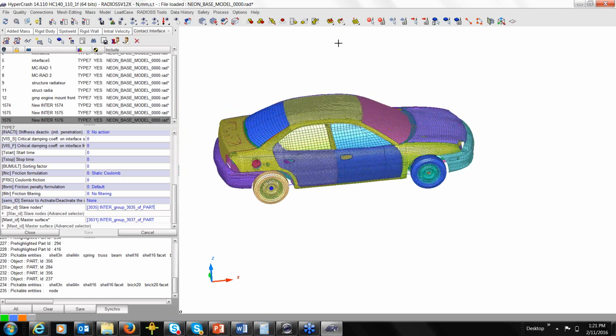The next thing I wanted to do is, okay, I have finished setting up pretty much my model. I'm not done completely yet. I'm running this analysis. I want to see some output request. So I need to put some information in data history, what we call time history, for me to be able to monitor those. This helps me do my post-processing.